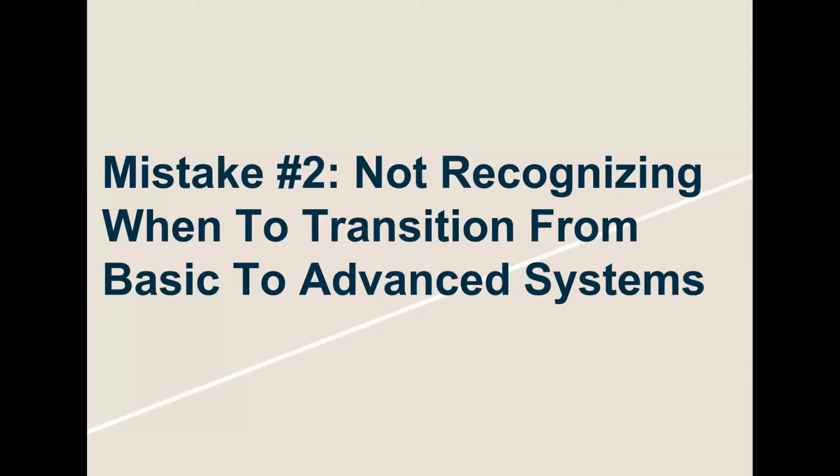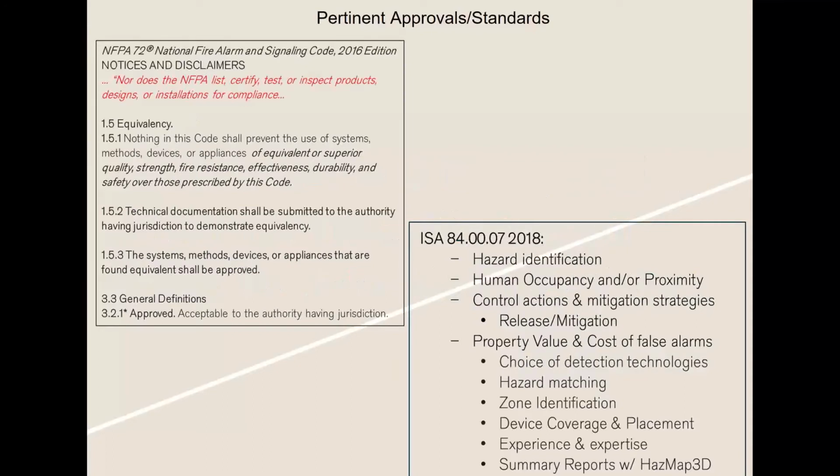Let's say we have a much larger lab space where we have tens of people in there and it covers a large area in square footage. It becomes more difficult to figure out, just by applying some rules of thumb, where to place these gas detectors. So there are some rules like NFPA 72 and ISA 84. What you'll note is a lot of gas detection companies, as part of their marketing, and we do that sometimes too, will say, oh, these detectors are NFPA 72 compliant.